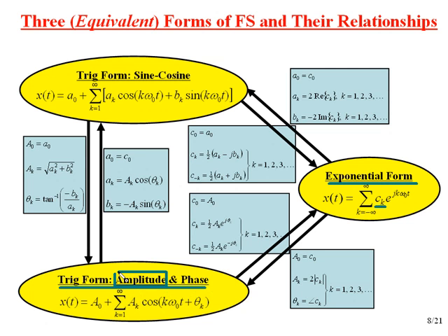of amplitude and phase. So from the c sub k, remember the c sub k's over here are complex valued. We need to get real valued amplitudes and also real valued phases. And so how do we do that? Well, you take c sub 0 and set it equal to a sub 0. You take the c sub k, but you only need to look at the positive integers. Remember, c sub k is defined for all the integers. We only need to look at the ones for the positive integers. You take its magnitude. Remember, c sub k's are complex, so you know how to take the magnitude of a complex number, and then you multiply it by 2, and you get the a sub k.